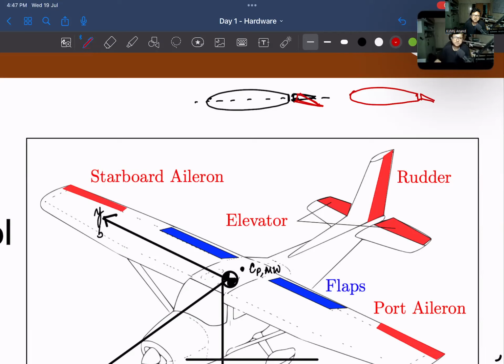Okay, so it's been a minute and enough of you are active. So yeah, other than two people having a small misconception, the lift is going to increase. Why? Because now the camber has become positive. I told you that asymmetric airfoils at zero angle of attack are going to give you positive lift. So earlier there was zero lift, now the lift is going to increase.